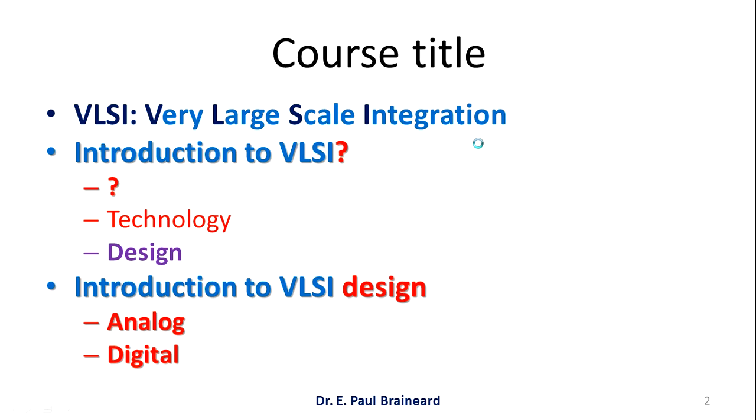For example, you are designing a MOSFET circuit. You have a metal oxide structure. The dimensions of these layers are also very important in this course. For example, what is the thickness of oxide? Even though this parameter has more to do with VLSI technology, still a VLSI designer should know the importance of this parameter. Oxide thickness and area.